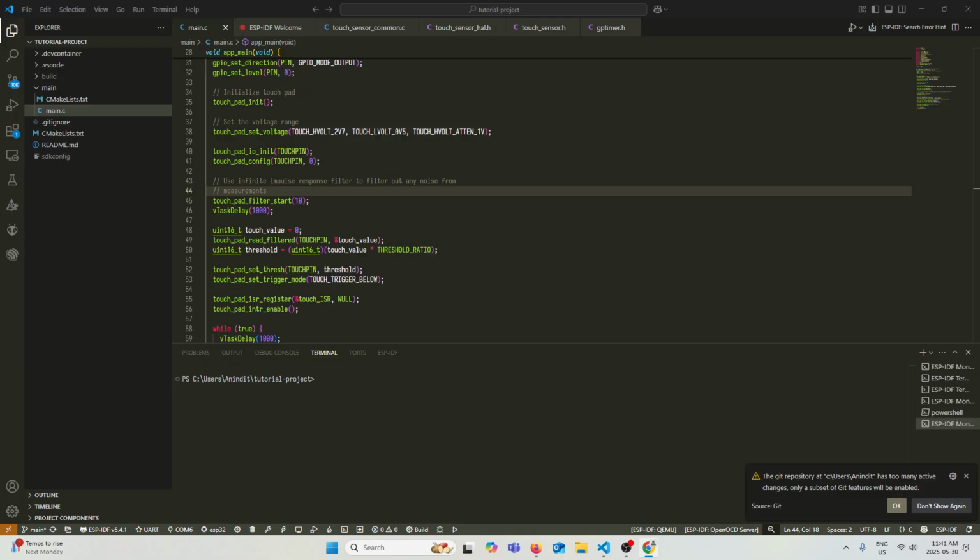The next type improves upon the ramp model, being slightly faster due to its special counter circuit known as a successive approximation register, or SAR. This ADC starts with its most significant bit, comparing it to the input.